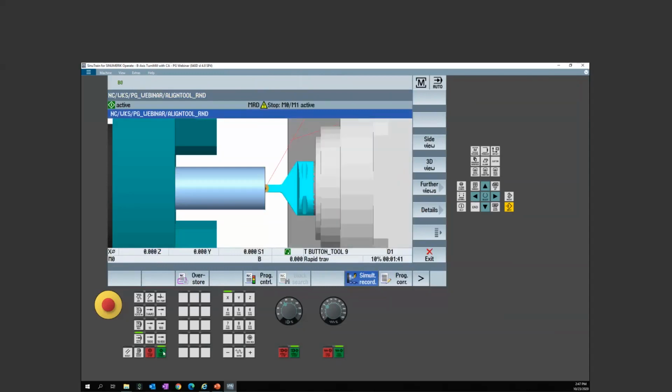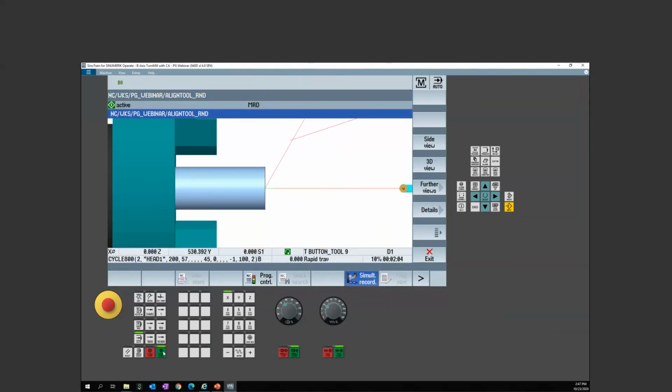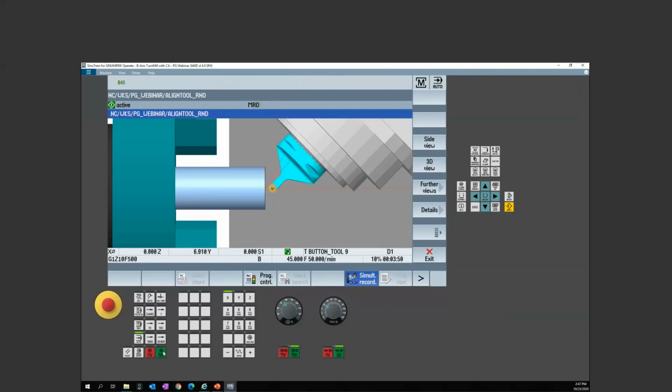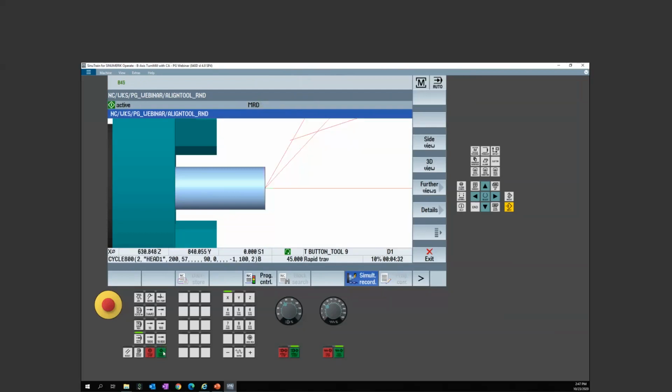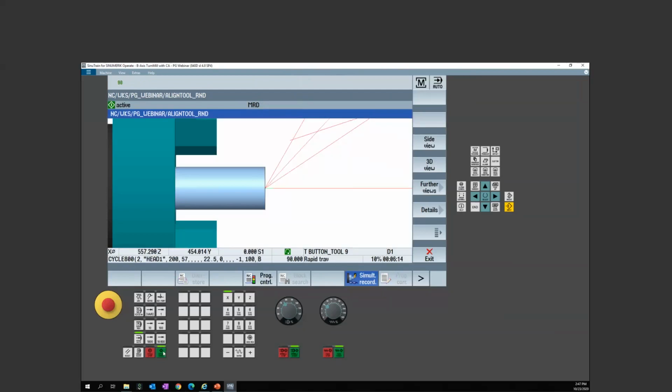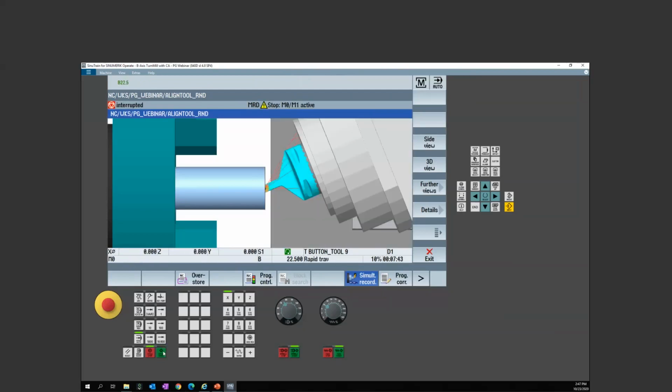So now it's up to my tool path to then shift or compensate for the radius of the tool. The only downfall here potentially could be that if I have an insert issue, I have to make sure I have cutter comp there too, where I can do a cutter comp wear strategy or something, or I would have to repost for any issues there, because I would be letting the CAM system now compensate for the radius. And my tool offset would work from the center to gauge line.